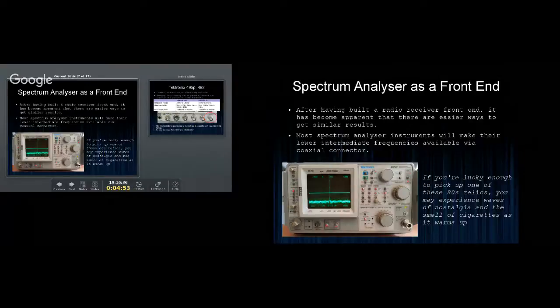What's interesting about them is they are effectively a complete radio receiver, a very low noise, highly configurable radio receiver. The way they work is they continuously sweep the radio receiver through a very broad range of signals, and then they only look at the magnitude, and that's how you end up with a sweep that represents the spectrum power.